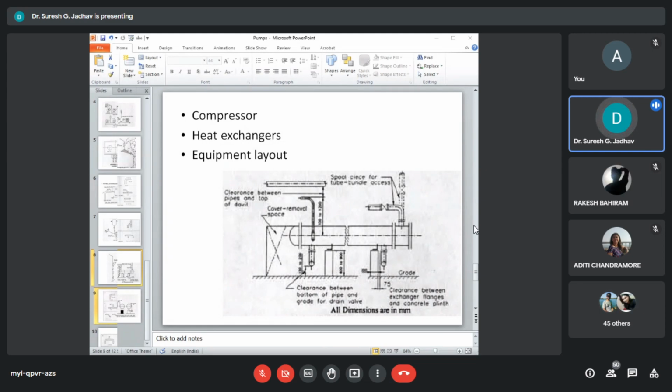The heat exchanger between process equipment and the battery limit, for example a product cooler, should be located near the battery limit to reduce the pipe run. Stack those exchangers which can be grouped together to simplify piping and save plot space. Leave space and access around the exchanger flanges and heads, and tube bundle cleaning or pulling space in front and in line with the shell.